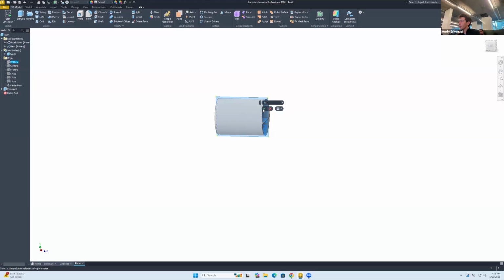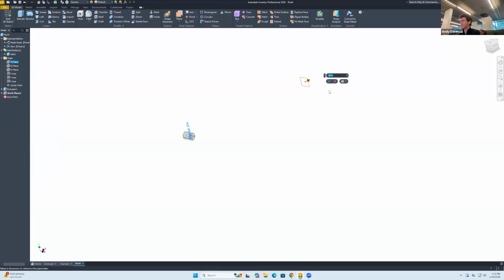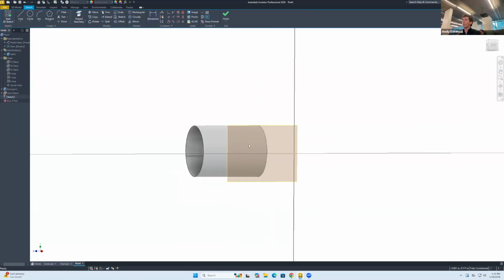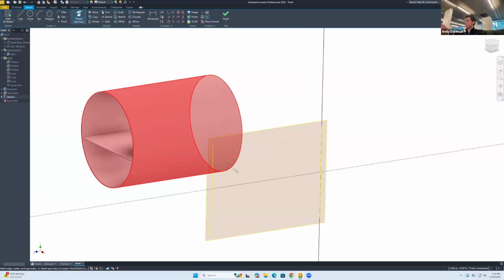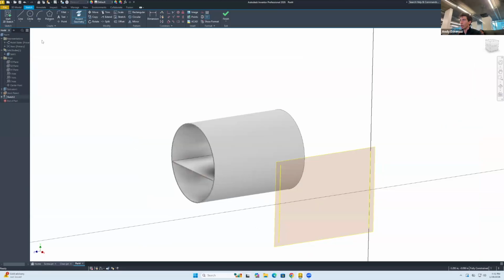Well, that doesn't matter. Oof, that actually does matter. Edit dimension. We're gonna make that too. Okay. And we're gonna do a sketch in this face. And all I want is to project geometry, those two lines, and that little point in here.